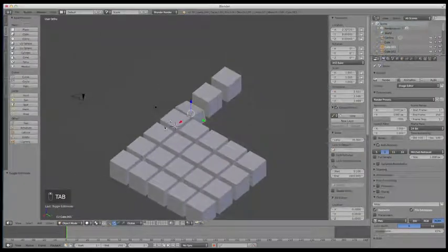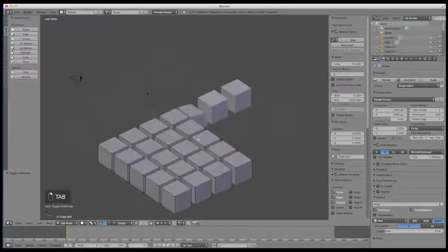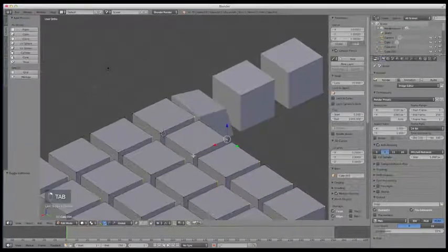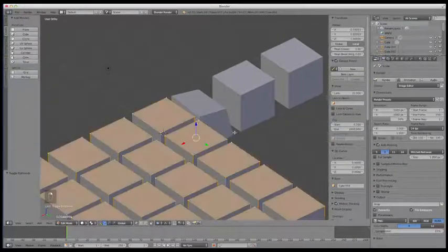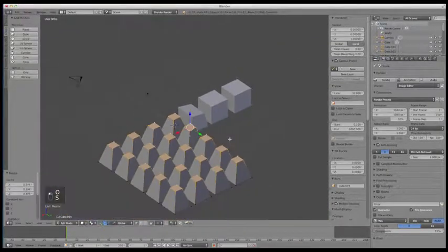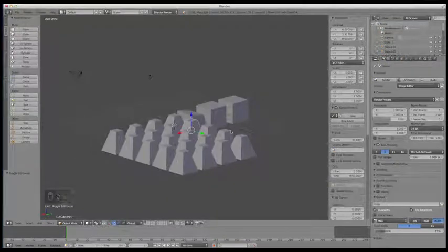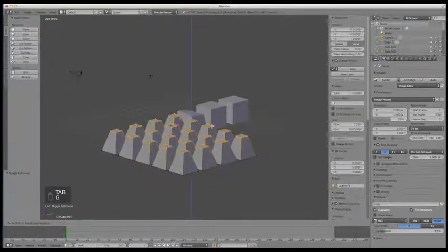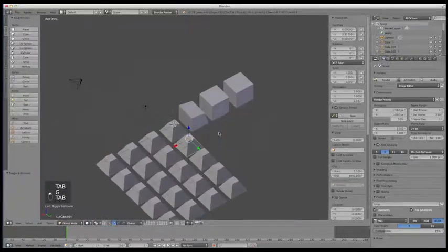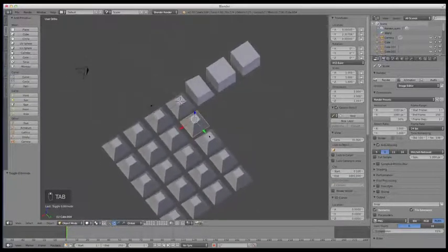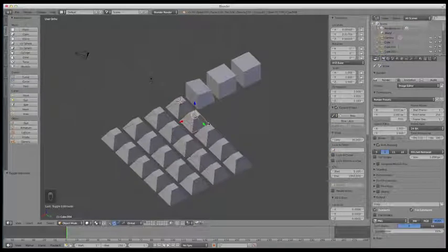But remember how we discussed selection and edit mode with linking? Well, the same thing works here because we've copied objects that are linked. If I go into any of these and I edit part of that object, let's say I edit this top face and scale that in, everything that's linked is going to be a copy of that. So it's going to do the exact same thing I do there. It might be a fast way to get in here and make some models. And those are always linked until you tell it not to be linked.